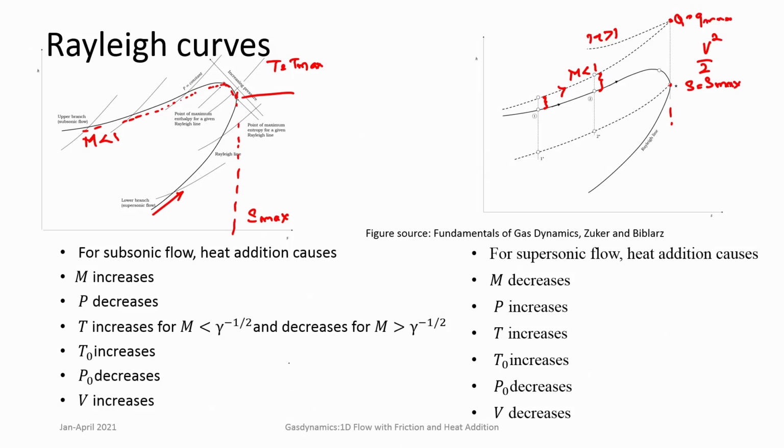So, this point is very important, and also notice that here you have a line. If you draw an isentropic line for a point 1, you have T naught corresponding to that, and T star corresponding to the point where it can be isentropically brought to Mach number equal to 1. Even this T star is varying, because now heat is getting added into the flow. So, T star and T naught are not constants.